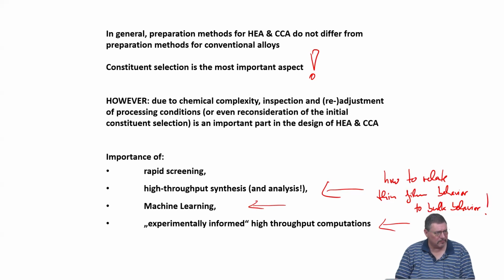This is not easy because you have additional stresses, you have a huge surface area, you have different diffusivities, you have maybe different quenching rates if you deposit the film, as compared to bulk processing. And so one has to be very careful there. This is done in abundance over the world, but I'm skeptical.